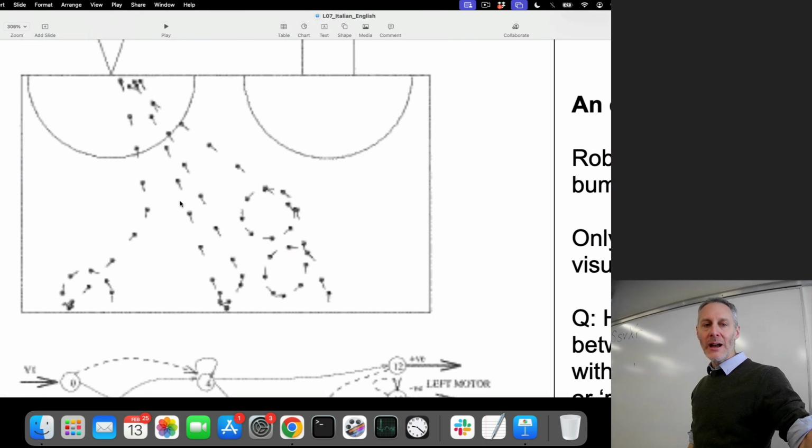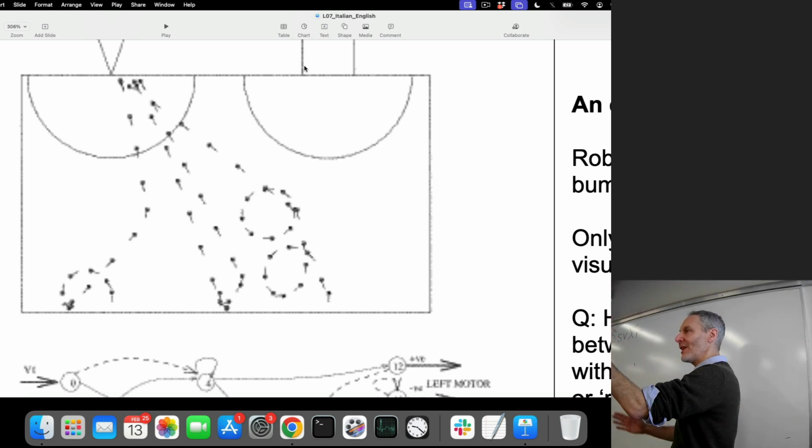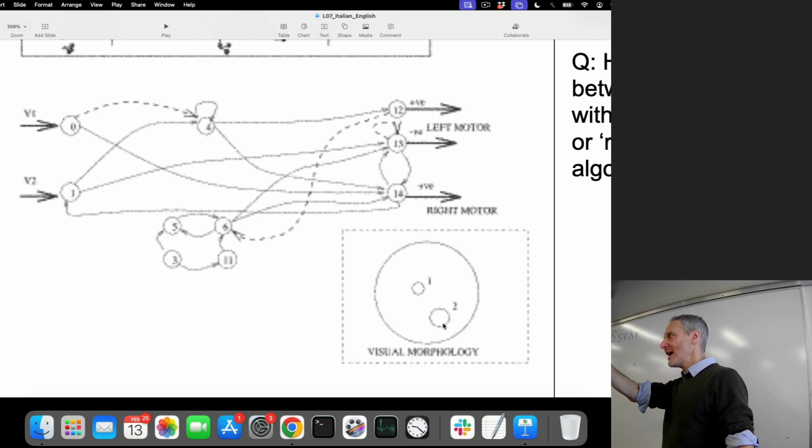Imagine the robot is turning and the black rectangle sweeps in from the left and never leaves its field of view, but sweeps from left to right along its panoramic view. At some point, fovea 1 goes dark, and then a short time later, fovea 2 goes dark. And then as things continue, at some point, half a second later, fovea 1 goes bright again, and then fovea 2 goes bright again. There's a time interval between the darkening and brightening of these 2 fovea.